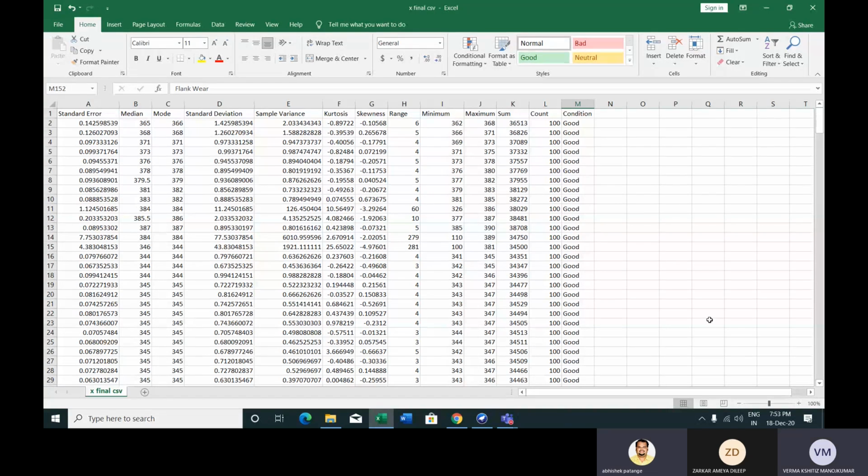But if the change in the amplitude of acceleration or frequency occurs only in smaller regions, then there is no use in calculating statistical features for the whole response.